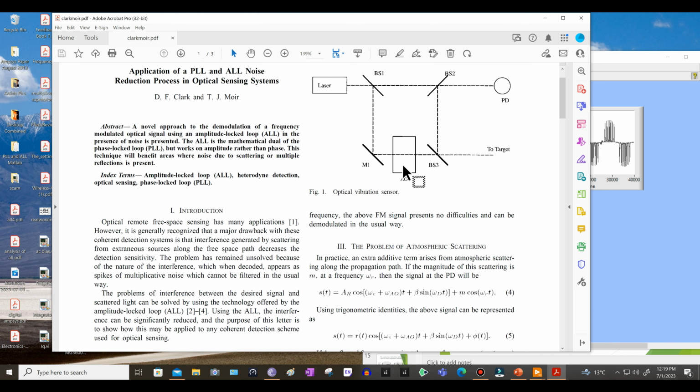I tuned it in for 100 megahertz, and we got 10.7 megahertz IF out of this with FM on it. And then from 10.7 megahertz, I beat it down to 455 kilohertz with a multiplier which I bought, and then we had 455 kilohertz. All had to be well screened and everything, obviously.